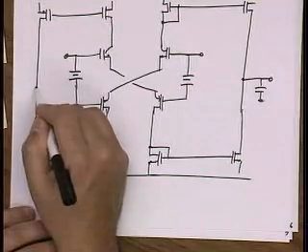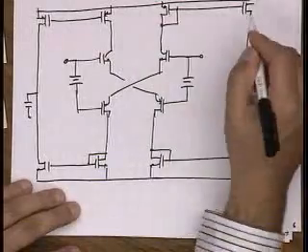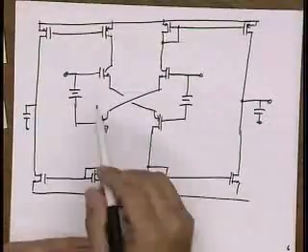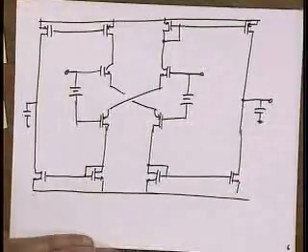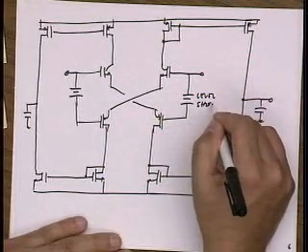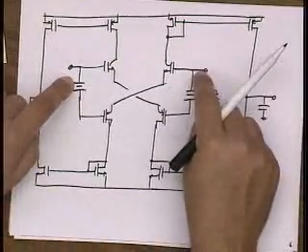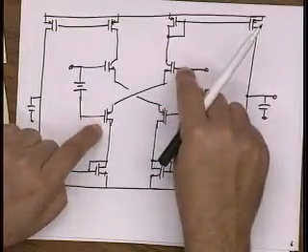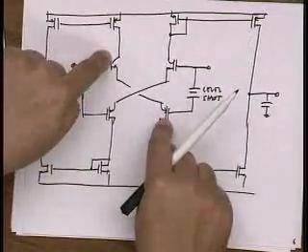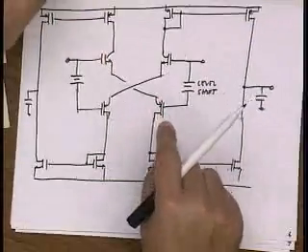Okay, so the circuit is symmetric. And to understand how this circuit works, notice that what I have at the core here is really just a GM block. Okay, these are level shifters. And the way to see that is if I apply an input, that input gets applied across two CMOS class AB stages. It gets applied across here, these two VGSs, and it gets applied in the inverse polarity across these two VGSs.